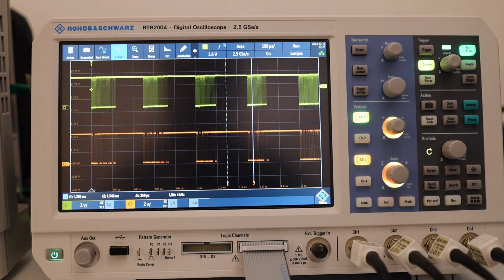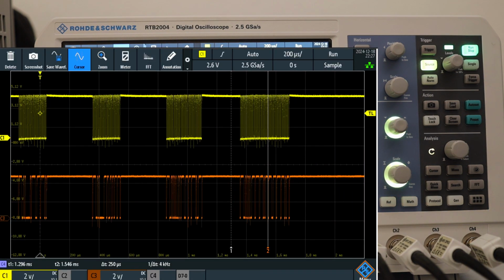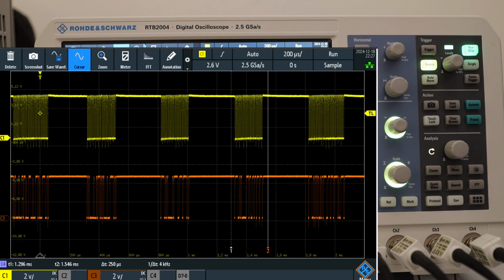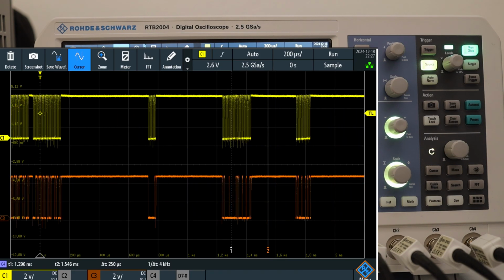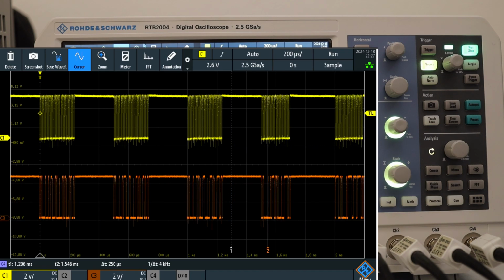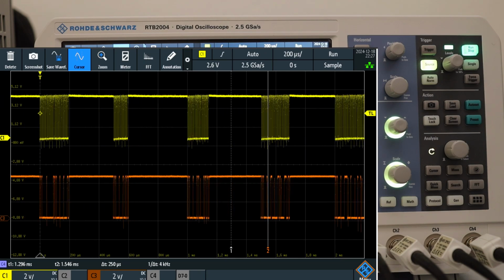First of all, to clean up the waveform, we're supposed to set up a trigger, and I'll show you how to deal with this waveform. In this situation, the flickering of the waveform can easily be solved by a basic trigger. You don't necessarily need to go all the way to finding out the protocol, trying to decode a bus and setting up a bus trigger. We will try to find a basic situation, and we will try to trigger on this basic condition.